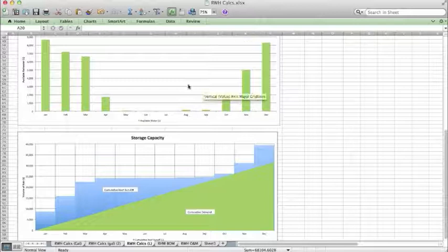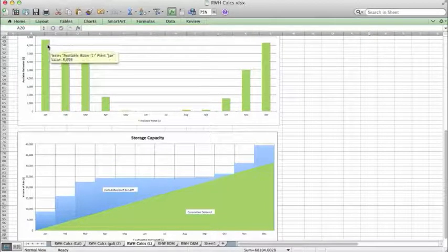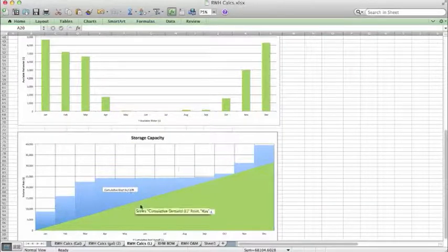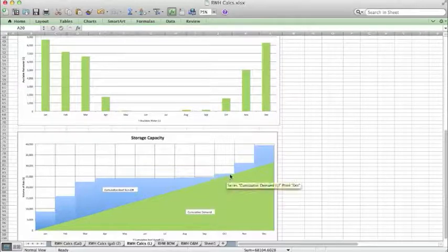All right, so if we see both charts here, this is the rain trend. We've got rain up through April, so we want to be able to store that capacity. And that storage that we have from January to April, we're going to use from May to September when there's no rain. And you see, as we get to September and October, we have very little water left because our consumption is getting pretty much up to our storage capacity, right?